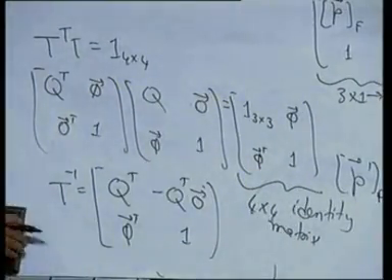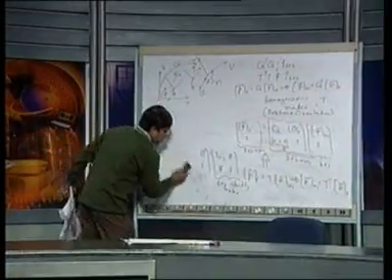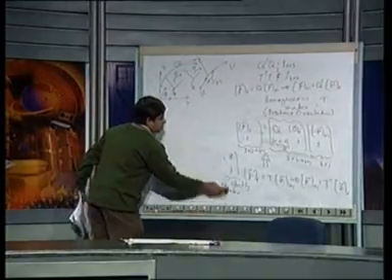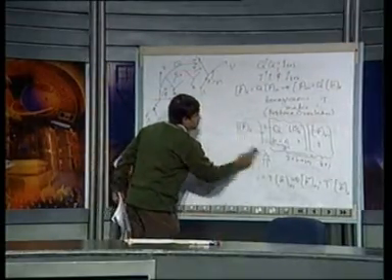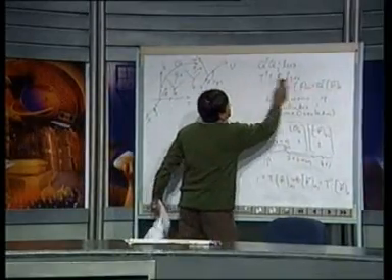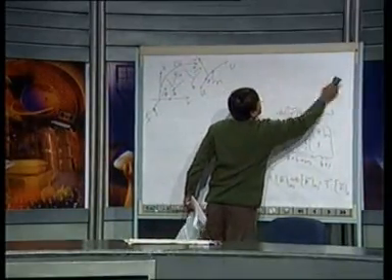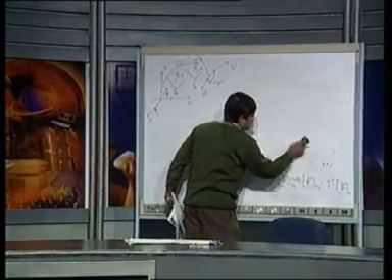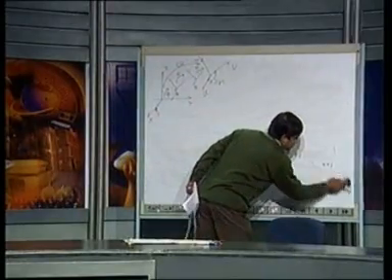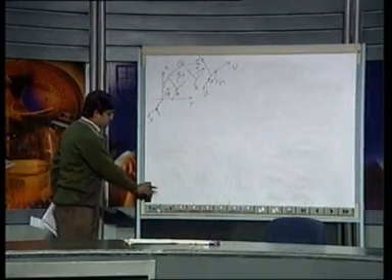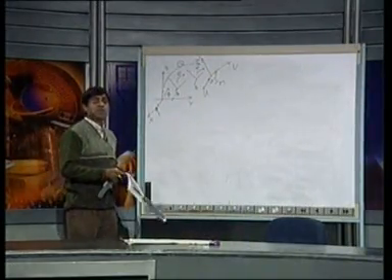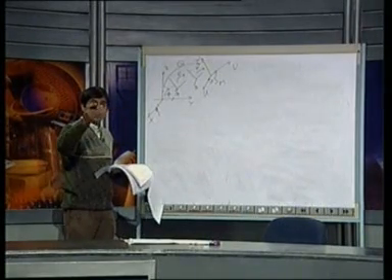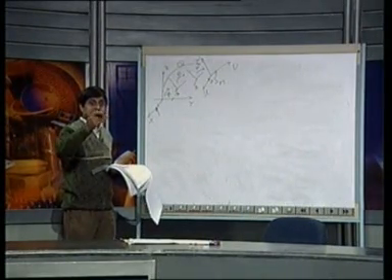So, now for a robotic system, when we have to do transformations from one frame to another, we have talked about the rotation case: if we have elementary rotations and from there we want to find the composite rotation, it is a series of multiplications of those rotation representations.